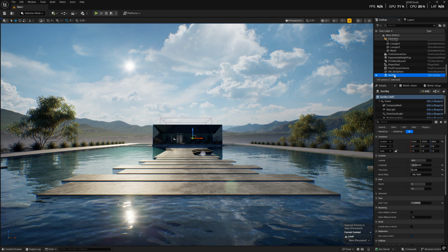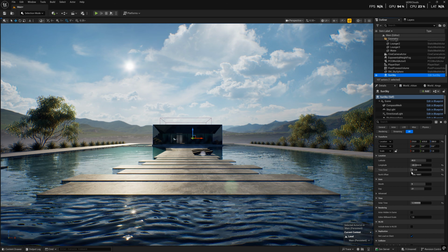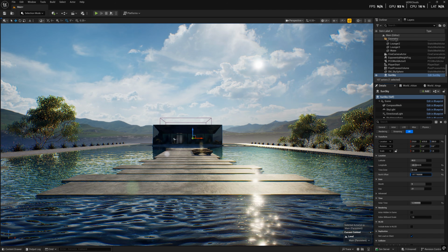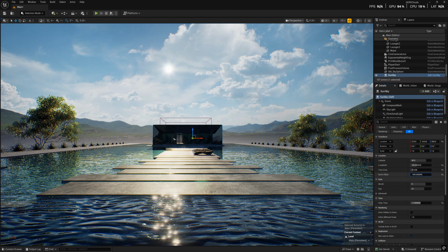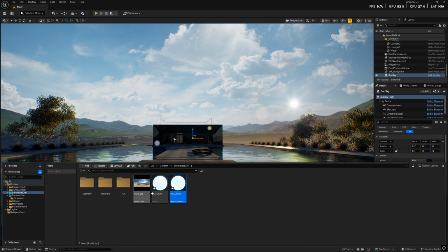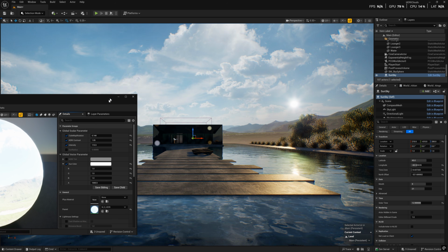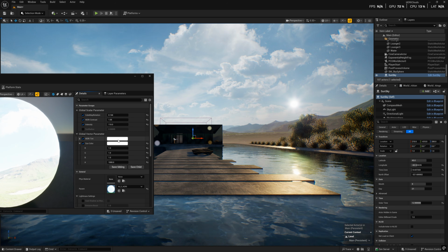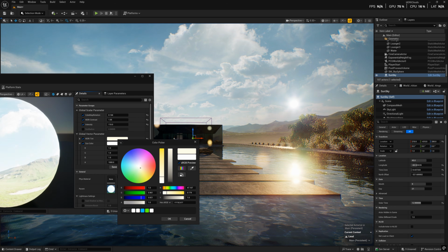Now, when you change the sun's position within the sun sky system, our dynamic sun will automatically change its position on the HDRI map as well. To create an even more realistic effect, such as a sunset, simultaneously animate the sun's position and the tint of the HDRI map using the HDRI tint parameter. This will add a cinematic quality and greater realism to your scene.